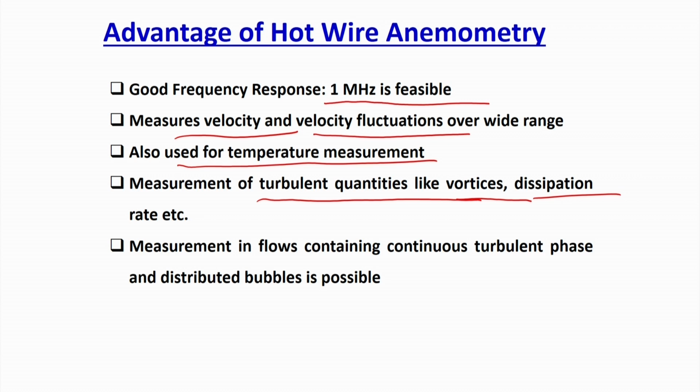Okay. It can measure continuous turbulent flow, and it can be used even for bubbles. In the Pitot tube the problem, as we discussed, is that if you use it for bubble flow, a bubble can burst and then the local pressure difference will be very high. So, in case of multi-phase flow, the Pitot tube applications are lower, because if you have a distributed bubble you can simply use this, okay, the way I have shown in the example.